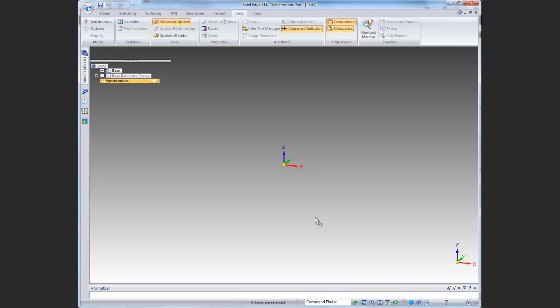Now last time what we did is we created 2 molds, and then we subtracted out the part from the top and we subtracted out for the part from the bottom. This time we're going to do what's kind of a more common task, and that is we're going to make both molds here, subtract it out once, and then divide the mold in 2. And that's kind of the most common task you'll do for your projects. So let's go ahead and start off by making the mold itself.